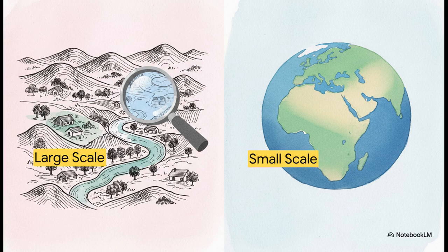A super vital part of that context is the map scale, and cartographers divide maps into 2 main categories, large scale and small scale. Now, definitely pay attention here, because this can feel a little counterintuitive. Large-scale maps, like topographical or property-based cadastral maps, actually show a relatively small geographic area, but they display a massive amount of incredible detail, down to individual properties, tiny buildings, and even small streams. Small-scale maps, on the other hand, think of the ones you'd find in a classroom wall atlas, show a really large area, like an entire continent, but with a distinctly small amount of generalized detail.